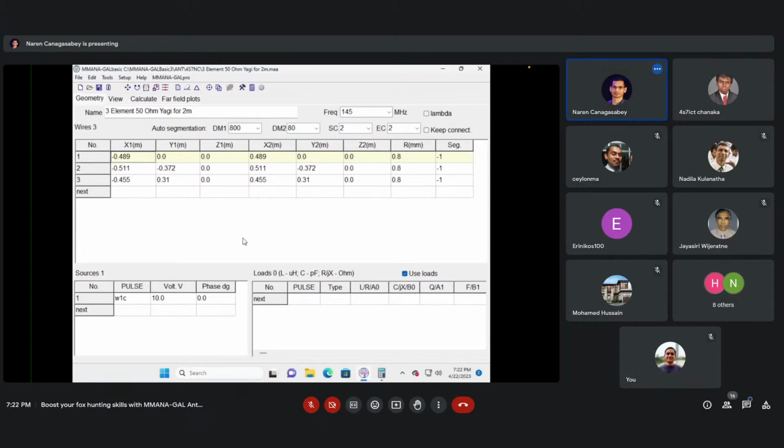How we got 0.473 is generally you tweak the measurements in such a way as to optimize the feed point impedance and the gain. By changing them slightly, you can basically optimize the antenna. So as opposed to 0.5 for a full sized half wave element, by taking 0.473 you're slightly optimizing the antenna.